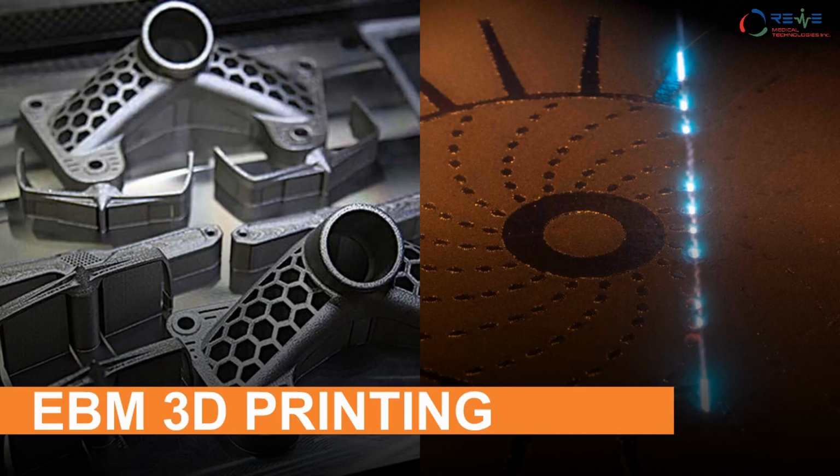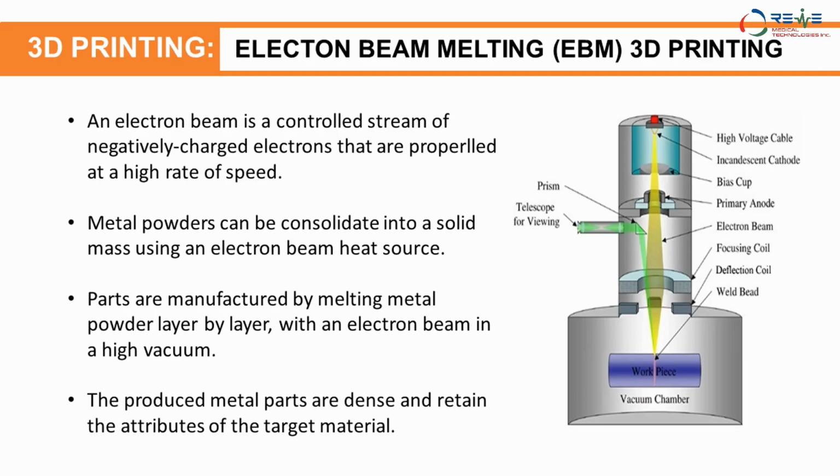Okay, next comes electron beam melting 3D printing. I wasn't personally familiar with this concept, but I read it up and I started to understand it. This is another type of technology where, instead of using a laser, they're using electron beam welding. An electron beam is a controlled stream of negatively charged electrons that are propelled at a high rate of speed. Metal powders can be consolidated into a solid mass using an electron beam heat source. Same principle, they can melt the metal by directing the electron beam on it. It will heat the metal up and it will melt and weld.